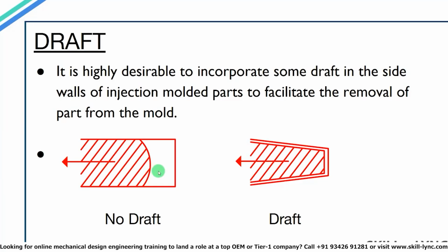So all the plastic parts that you see around you that were created using injection molding, all of them have drafts. The amount of draft angle that needs to be provided will depend on the polish and surface finish of the mold tools, and this polishing done will depend on the customer requirements. For example, it is more difficult to remove a textured component, so higher draft angles will be provided for textured components. And all the components that you see which have a glossy finish have been made using high polish tools, and thus lower draft angles will be required for their manufacturing.